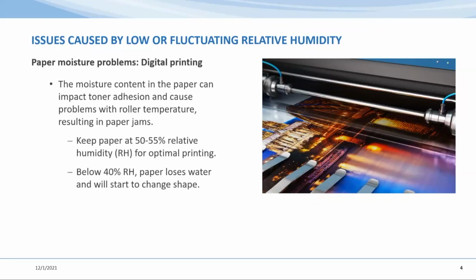When we have lower, fluctuating relative humidity, the toner adhesion, how well the ink sticks to that material, decreases. And we can have problems resulting in paper jams, for example, or smearing of that ink if you have bad adhesion.